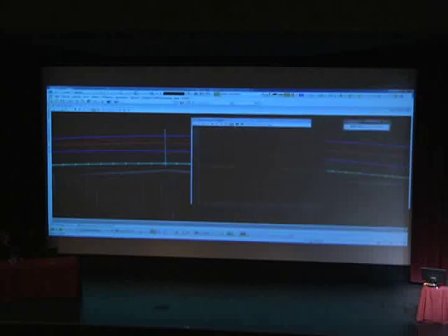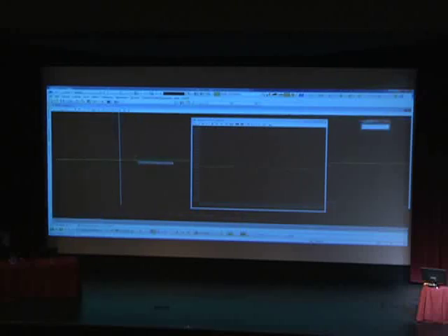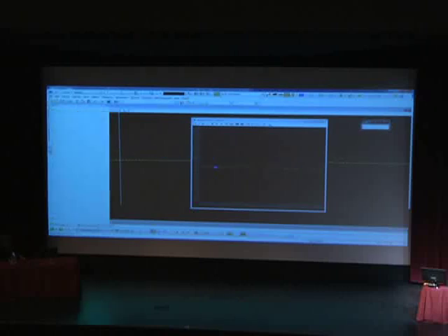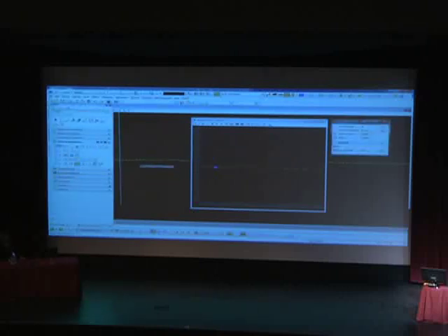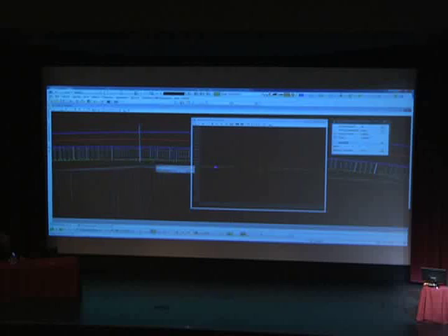and that's because my terrain is set as active. All right, next I want to reference in my edge of pavement profile into this view too. Now, this is going to be the process that I see us using in the sense of referencing in multiple profiles. Like before, you had your vertical alignment generator, the green cell, and you needed to plot multiple profiles. I see us doing it more like this.